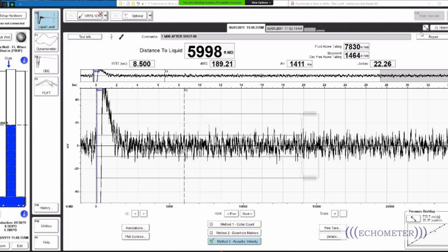And this well had a series of shots. We started taking the fluid levels just a minute after shutting the well. And here's a small preview of what we'll be reviewing on this well. So the first shot was taken 1 minute after the shut-in, and then consecutive shots at 6 minutes, 11, 20, 25, and so on.